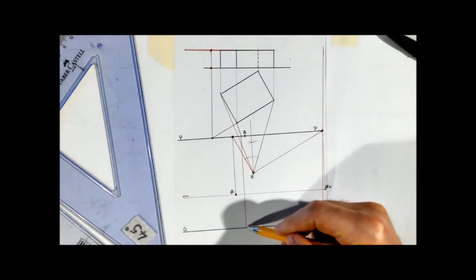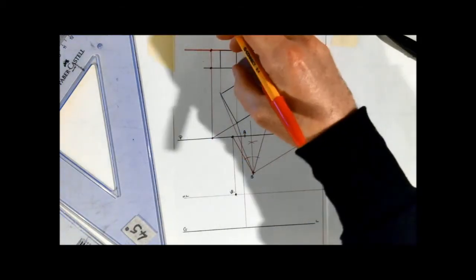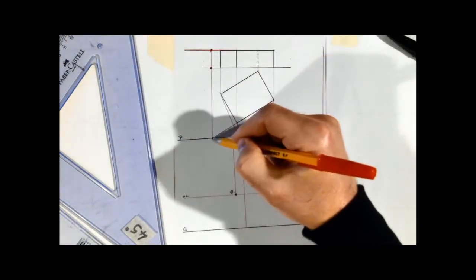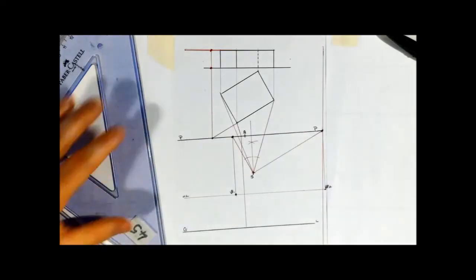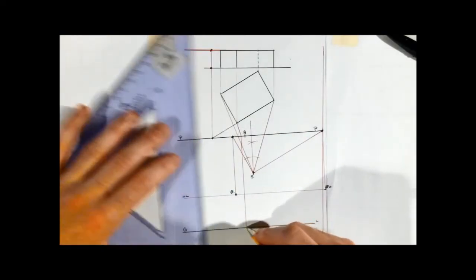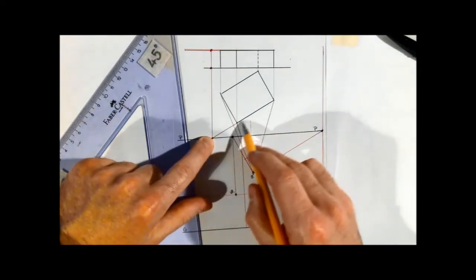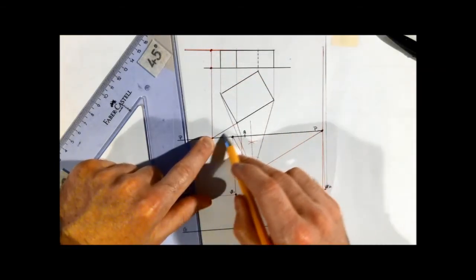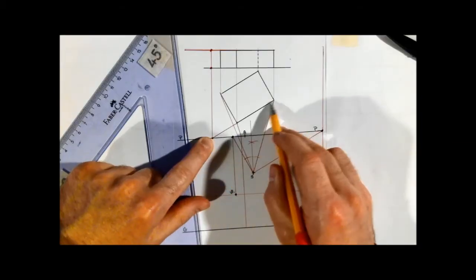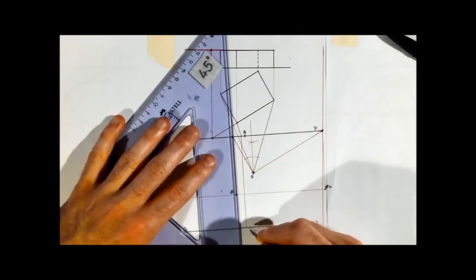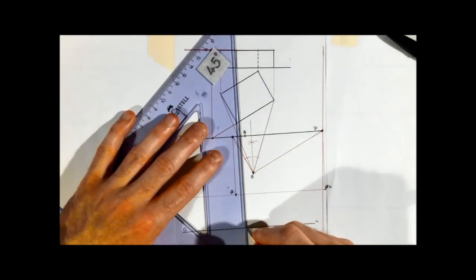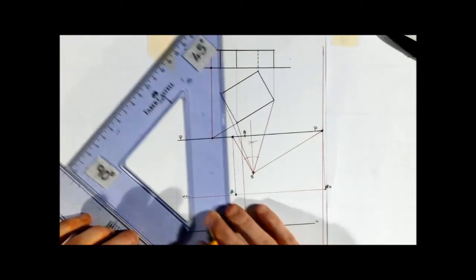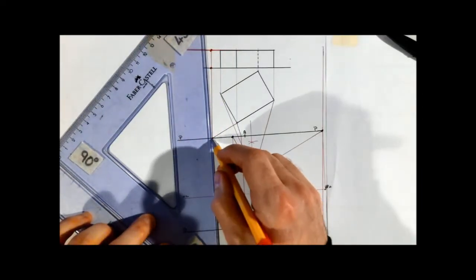I cannot from here measure up to 15, which is that, but out here I will be able to, and I'll bring it down. And to be able to do that, I'll show you now. So, as we have located this point, I project it down here. Up here I was just showing you the understanding. I've projected down here to my picture plane. I've extended the line down. And from there I'm going to come down parallel to my line of sight, to where it hits the ground line.